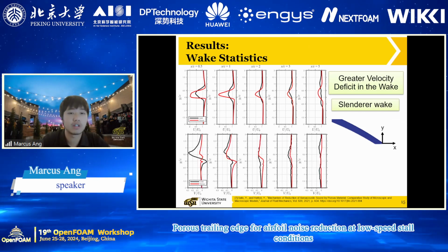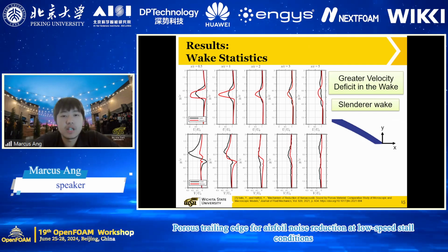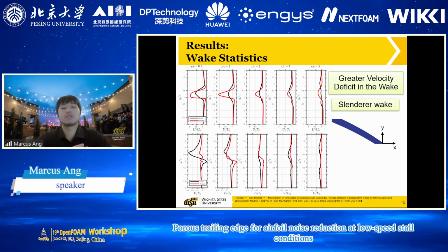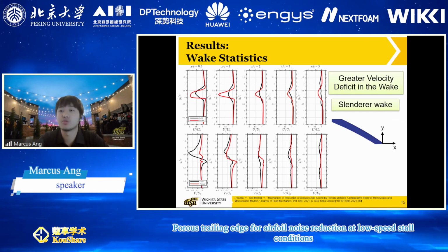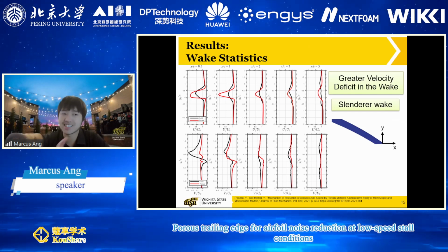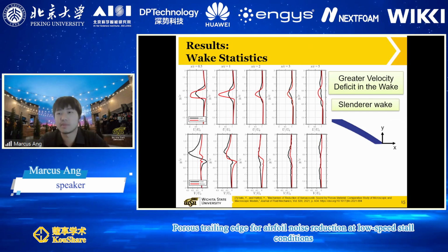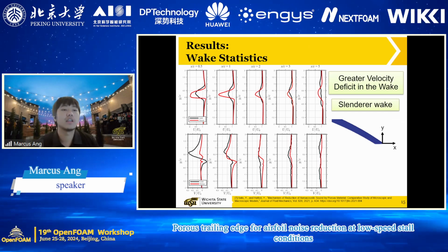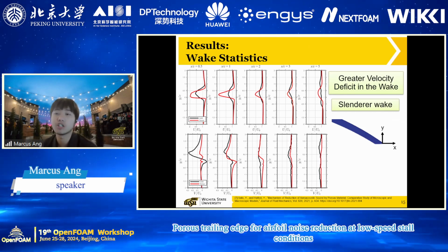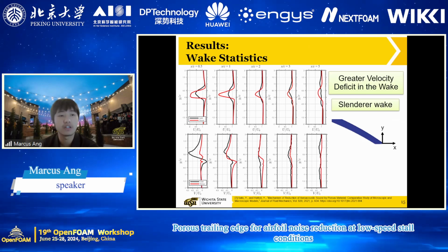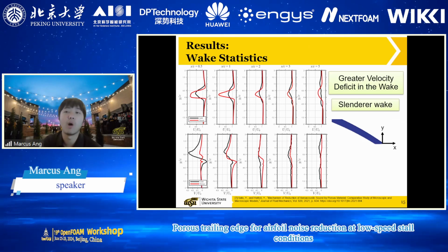When we look at the vertical direction, there's a couple of changes here. The first thing I want you to notice is that the vertical component of the mean velocity shows regions of reverse flow. And this is evident through sign changes. When you see that kind of zigzag shape, that is directly related to a vortex that's being shed, essentially. Now, interestingly, at 0.5 chord length away, the solid airfoil represents the strongest variation in the vertical velocity, while the porous case only shows high variation about 1 chord length away.